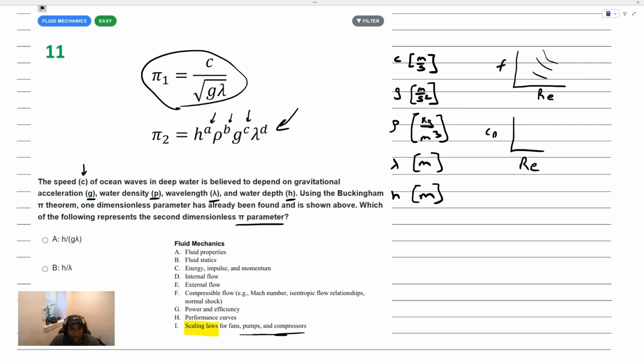parameter. The first thing is determining the number of fundamental units that you have in the problem, dealing with mass, length, and time. So your option is 0, 1, 2, or 3. I can see we have a mass, kilograms, we have a length, meters, and we have time as well, seconds squared. So we have 3 fundamental units in the problem, and the total things in the problem that exist, we have 1, 2, 3, 4, 5 variables. If I'm looking for the number of pi parameters, I just take my number of variables and subtract off my number of fundamental units. So this problem is characterized by 2 pi parameters.